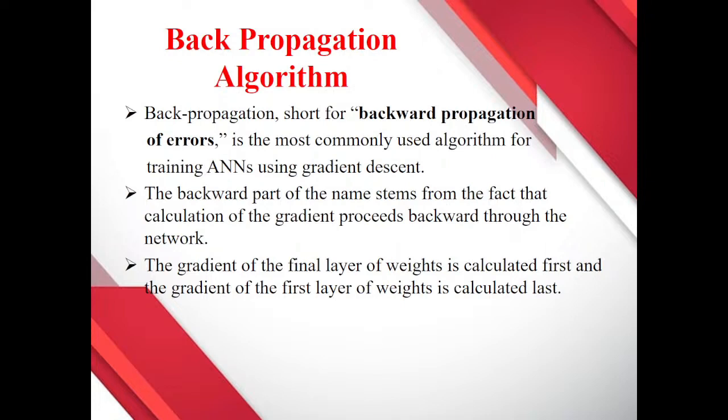There is a formula: del Wij is equal to minus dou E total by dou Wij. We have to do that adjustment in manual calculations, and then we will get the optimal ANN structure. This we are going to use to classify signals, different types of disturbance signals.